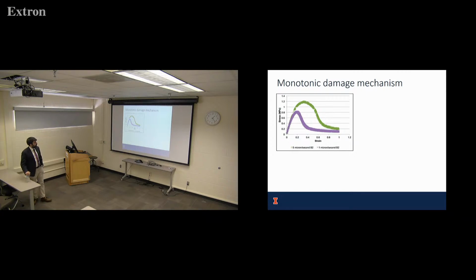We did run some tests later on aged binder. We've run a lot of poker chip tests on aged binders as well. And we do see that strength continues to increase, but also a much more rapid decrease, a loss of flexibility probably. And how about the failure mechanism, like the cavitation process, does it change significantly with aging, or is there some other response? Because in the unaged condition binder, the cavitation process might be a little different. Definitely.